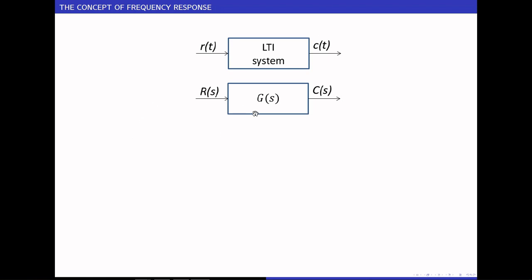So here the advantage of Laplace transform is this output C of S can be written as a product of G of S and R of S. It is simply an algebraic multiplication. So therefore, if I'm interested to find out this C of t, only thing what I need to do is take an inverse Laplace transform on G of S R of S. If I take it on this particular quantity, I will get C of t. This is what we do usually in time domain analysis.